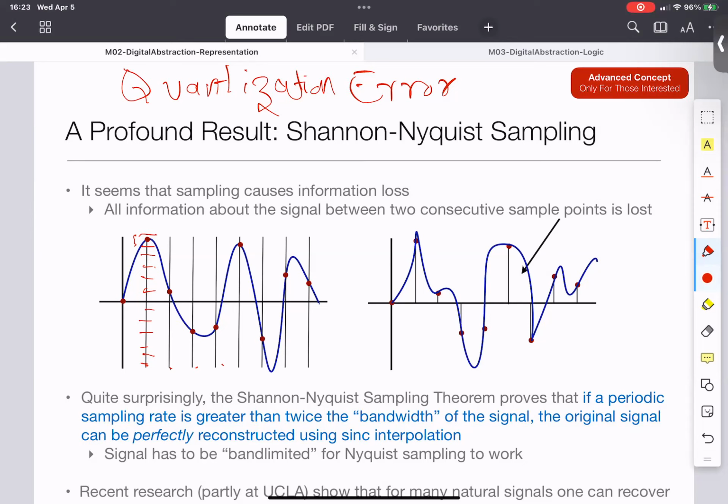Those usually use 24 bits, meaning the set has 2 to the power 24 elements. The reason is that seismic waves have a large ratio of max to min, what's called dynamic range. They can span a large range, and we often need to measure very tiny signals. Okay, so that's an example.